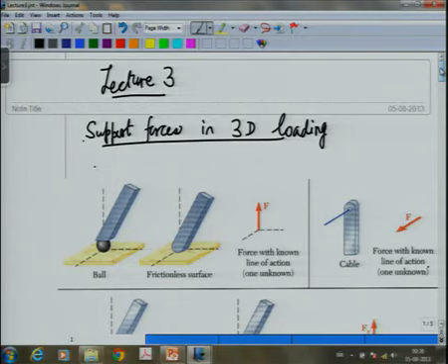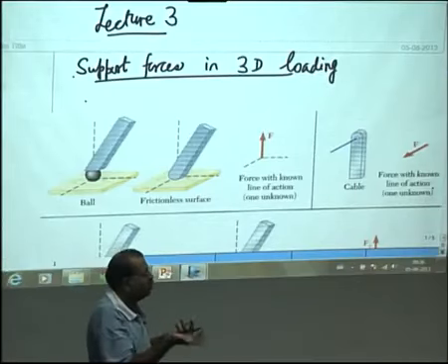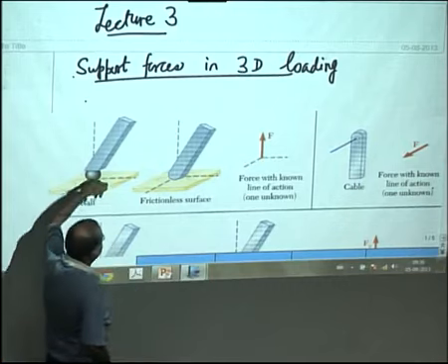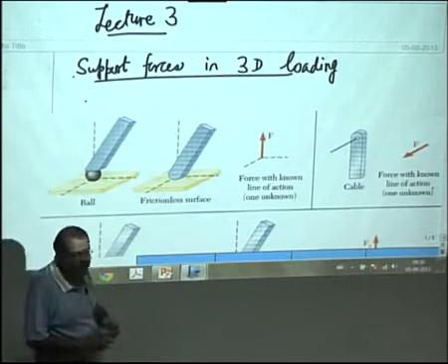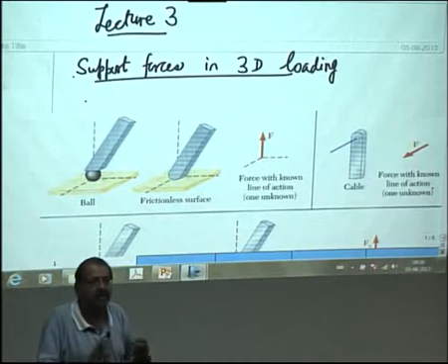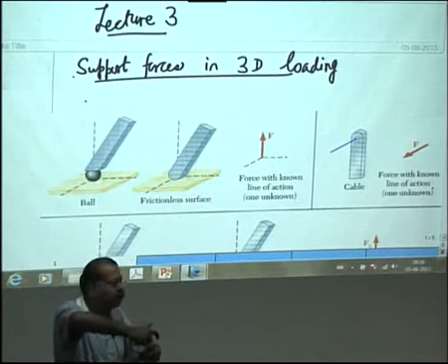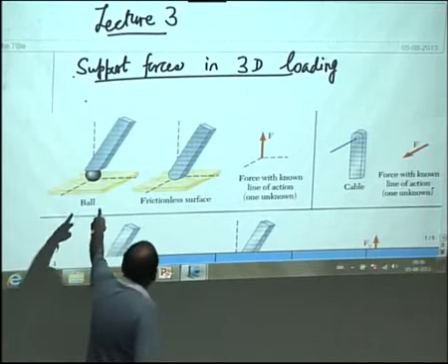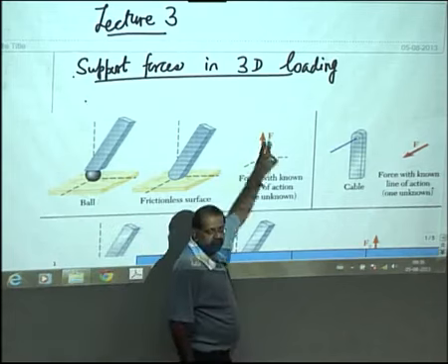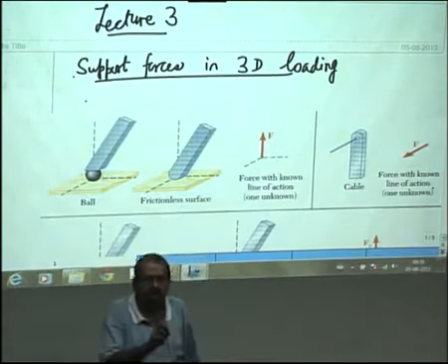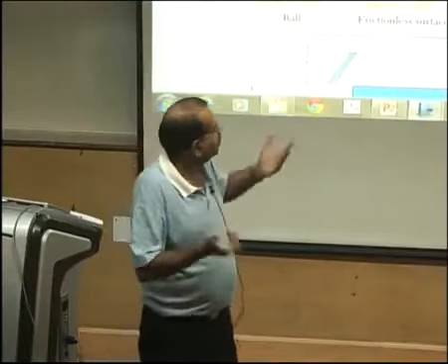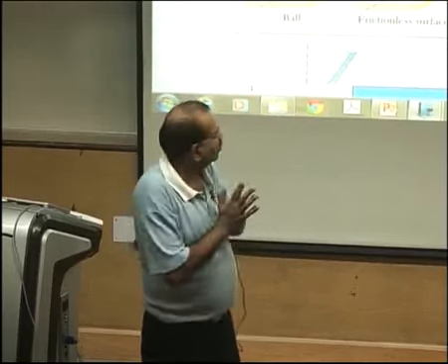But you try to move the body along z, and obviously here the loading is such that it will go down. If it is up, it will move up, there will be no contact forces. But if you try to move the body down vertically along the z axis, you will find that it will not be able to move. That means there will be a force. Whereas if you try to rotate the body, it will rotate about all the 3 axes, so there will be no torque, and therefore in cases like this, the unknown reaction will be a single force. What do I mean by single? Its direction is known. If the direction is known, that means there is just one scalar unknown.